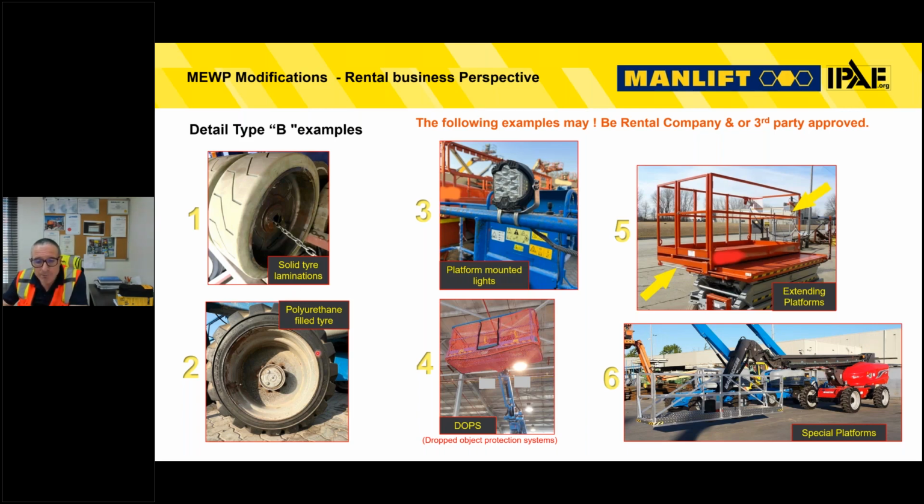And the same if the rental organisation or others are refilling tyres with polyurethane, the foam that goes inside the tyre. We have to use the correct product. It needs to be filled to the correct pressure. It needs to cure to the correct hardness, the correct durometer rating or shore hardness rating of 25A or 45A, for example, to make sure we're not causing a stability hazard by using the incorrect product when we're putting that product inside the tire.